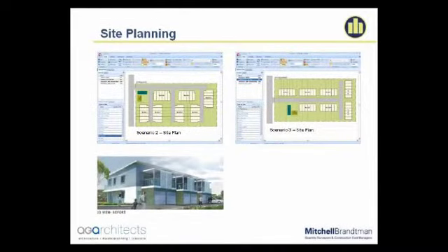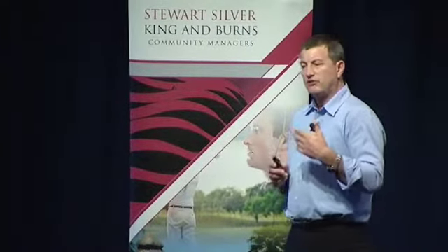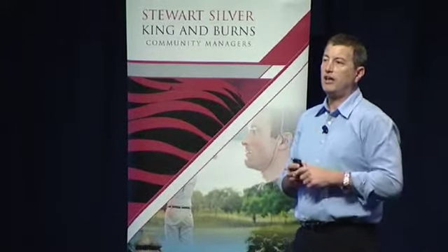Now looking at Adam's model, this sort of process works around collaborative design. So it's Adam and I working together with a project. So we're working with a site plan in the first instance. That's the first cut, if you like. We start to look at, with a townhouse project, what do you do with the cars? And that's probably the biggest key issue. So how do you circulate around the site, and do you put them in a garage or do you put them in a carport? If you want things that are cheap, they have to be in a carport. So we start looking at how do we change that design so that we're accommodating those things. And the information is flowing backwards and forwards between Adam and ourselves.